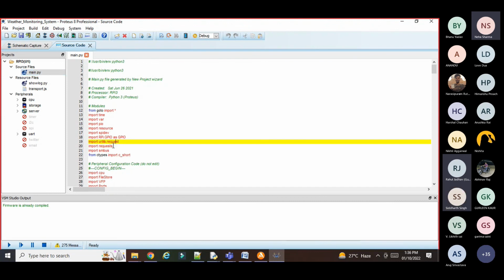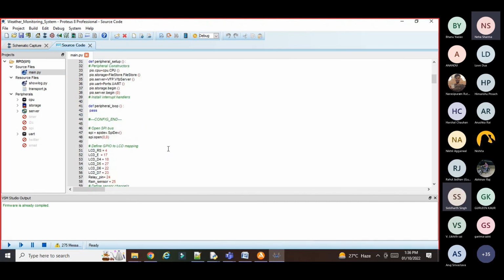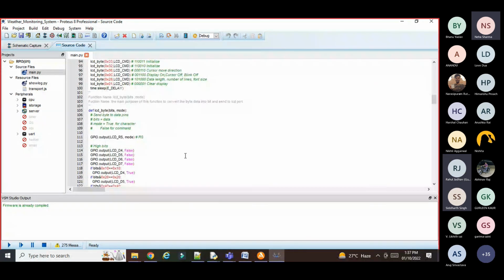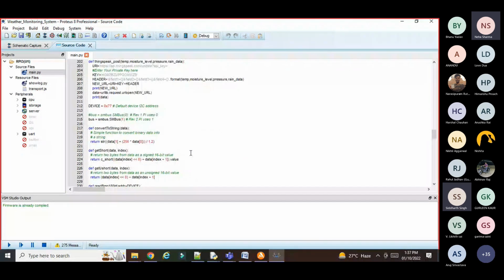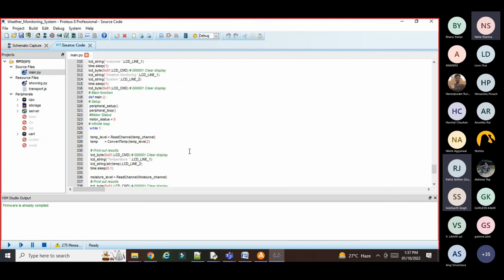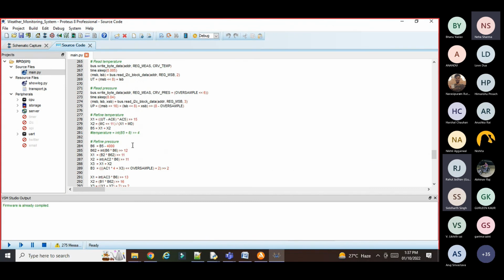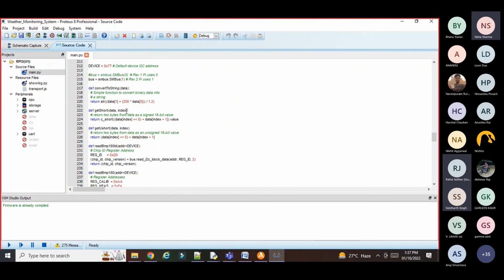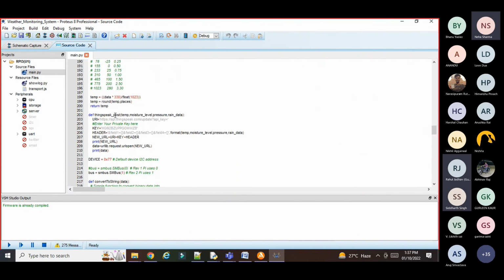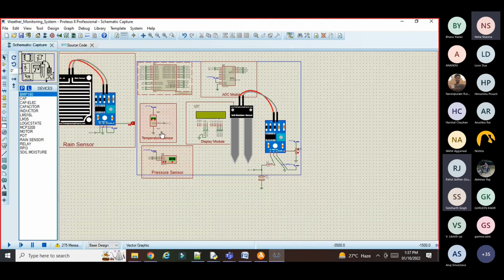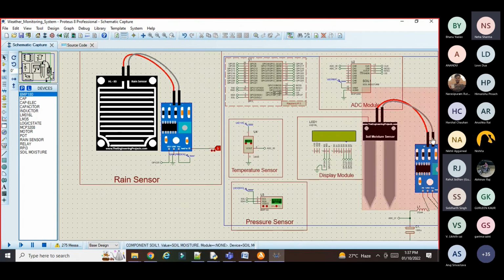Once you get all this input, and I already told you how to use the pin functionality, if-else loops, then it will be very easy, because if you see the programming part, it's all the same, like whatever I told in the basics now: to send the data, GPIO output, input, then convert the signal, set it to a variable, and use that variable. So that is the point. The most important part is you should understand the circuit first, and then you can start the programming.